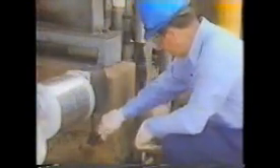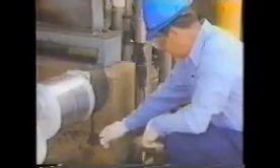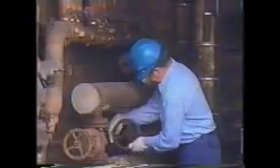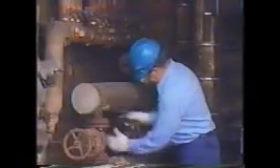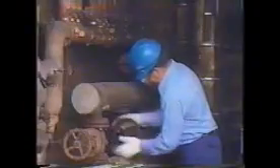The next step is to close the steam trap drain under the reboiler. This prevents the steam that is applied to the reboiler from escaping. Then he opens the steam supply valve to the reboiler. Once this is done, the reboiler is ready to receive the steam used to reheat the bottoms product.